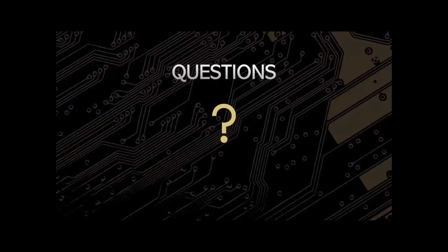All right, thanks. From Donovan McDonald. Should I be providing the drill file along with ODB files? I usually leave a drill chart in the ODB file itself. I'm sorry, can you repeat that question? Sure. So the question is, where do we put the drill file? Yeah, it's going to be either in your ODB++, or you can just throw it in your Gerber files. Usually they throw it all in one folder. I've also seen the copper layers and the drill layers in two separate folders, but either way, we look at every single folder and file inside that data package. All right, so as long as the drill file is included.